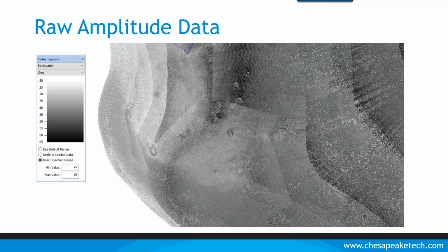So our main statistical tool for working with backscatter from swath systems is a technique called empirical gain normalization. And I want to spend a moment to describe exactly what that is. What you're looking at here is a small piece of the 2015 shallow water survey, and I've plotted the raw amplitude soundings as a map. You can see a little boat here, and there's some other targets on the seafloor, other wrecks, seagrass, there's light and dark areas.